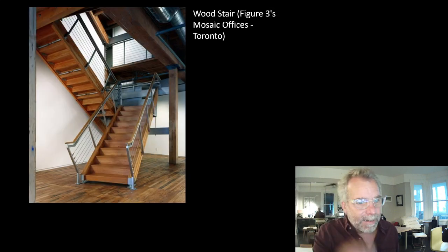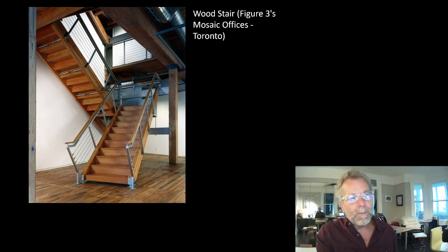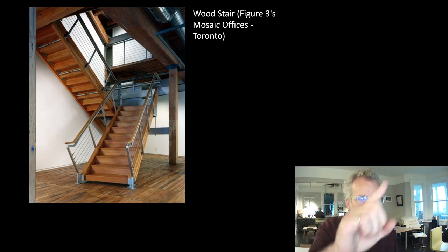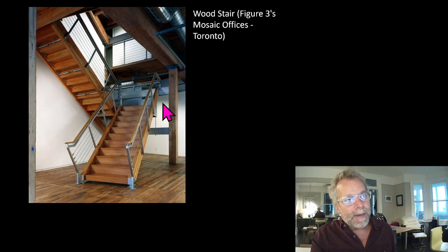This is one that I did that I'm particularly proud of. I did this years and years ago. It's a glulam stair with a switchback. And so it was a challenge to glulam. Steel is very easy to bend. We can put a full moment connection as we translate our way from the stringer into the landing. There's no problem having continuity in that joint. We can't do that with wood. Wood has to be straight elements.